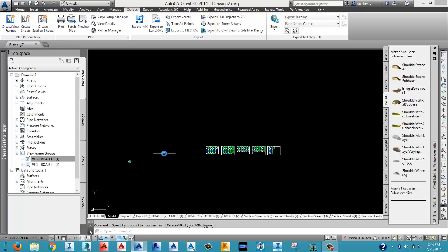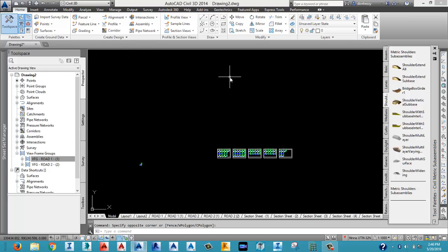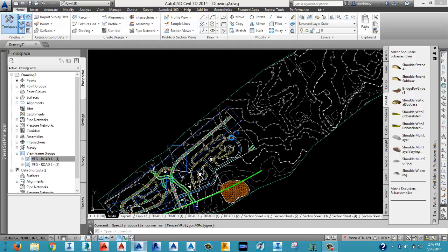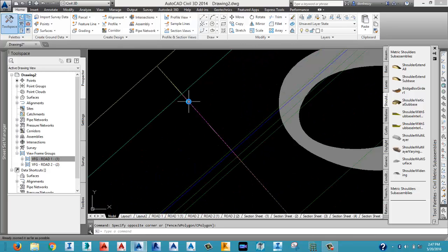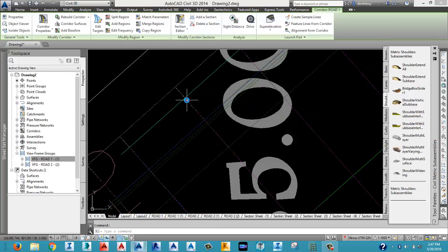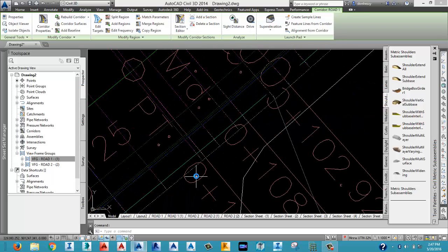So having that at the back of our mind, let's proceed now to earthworks extraction. That's volume or earthwork extraction. Still on my, okay, I can't have it from my sample lines. So what do I have to do now? All I have to do is select my sample line. If I'm working on road 1, I'll look for a particular sample line on road 1, and I'm going to select that sample line.